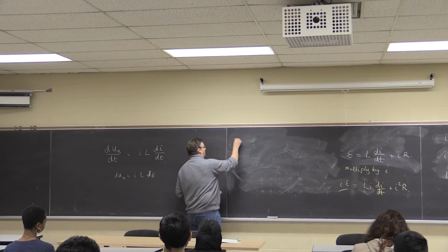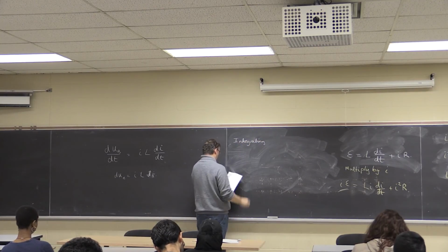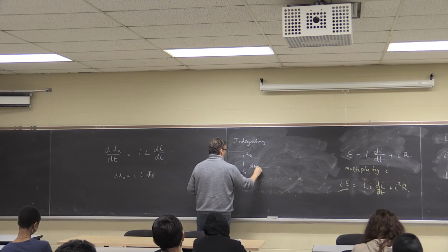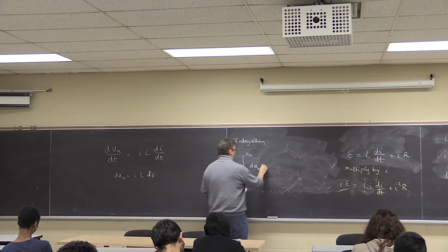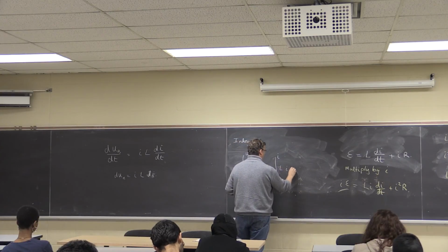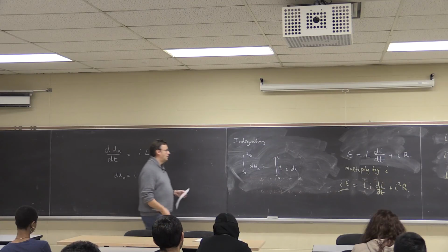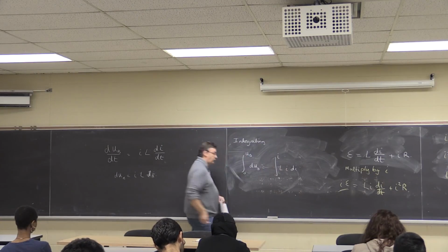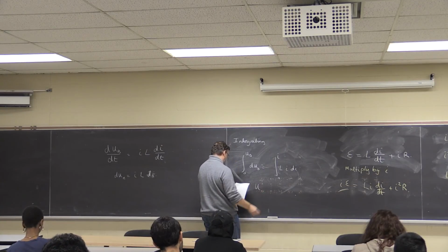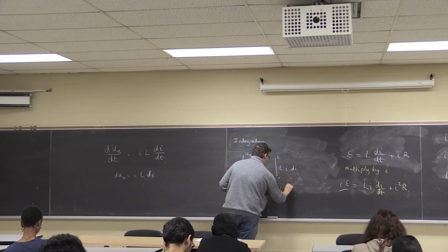So integrating, I'm going to go from 0 until it's completely full of energy, the integral from 0 till all the current is flowing of L i di. So L is constant, it's easy. Integral of i is half i squared. So basically if I play around with that, I get U_B is 1/2 L times i squared.